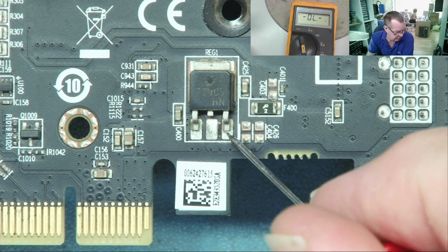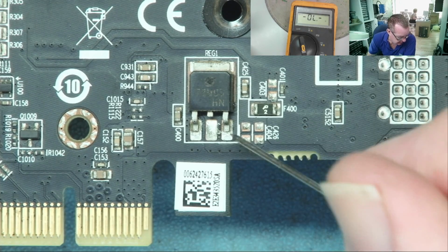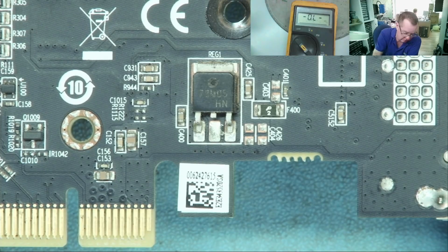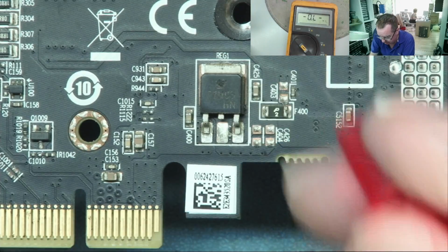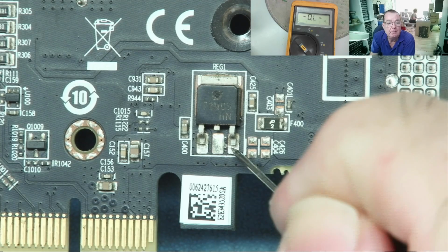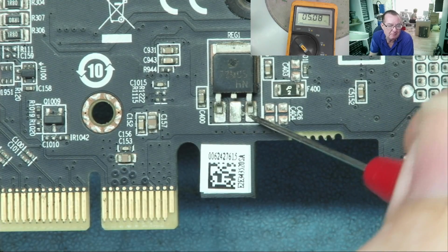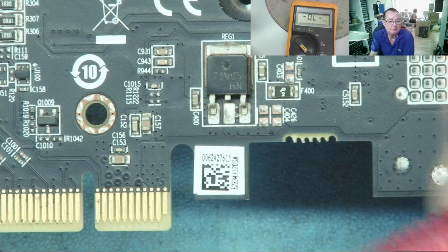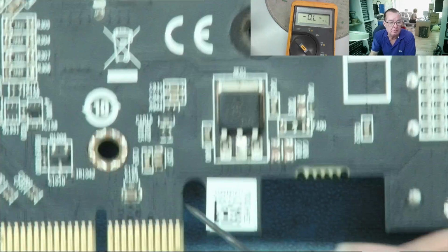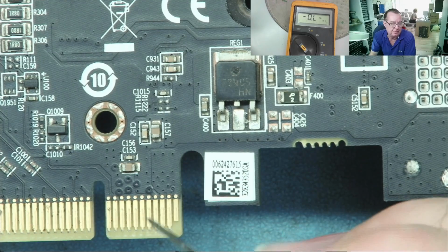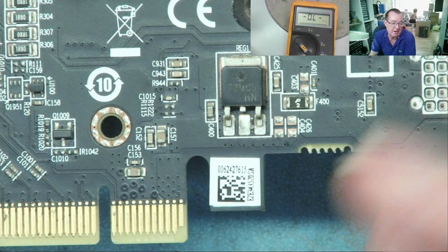And we'd expect this to be quite a high resistance. I mean, that's just reading very high. I was on continuity. Let's go to here. Yeah, I mean, that's like 5 kilo ohms. It's quite a high resistance, so that is okay. We also know we have a connection from the input to the 12 volts coming in, so we know that's okay. Sometimes there will be a fuse.